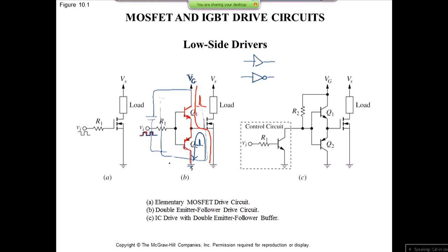So the reason that you're doing that is your main source, which could be further down, may not be able to handle high impulses of current. So locally you add a cap over there to do that. So even though this current is a pulsating current, over here you can see it's much smoother. And that means if there is other stuff connected to this source, they are not going to see as much noise.